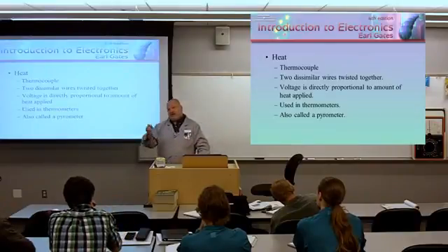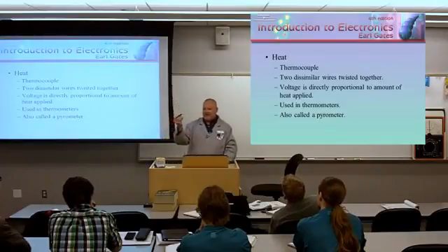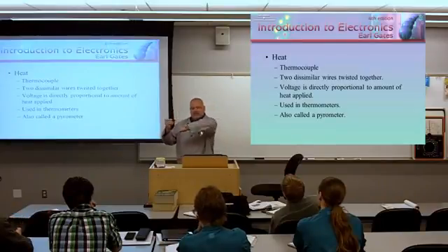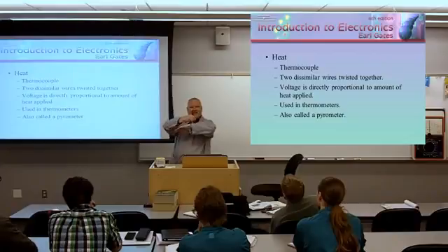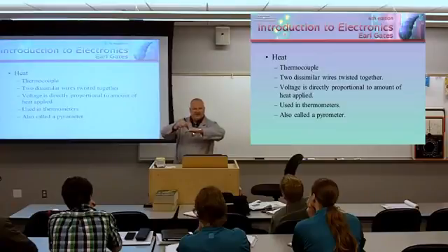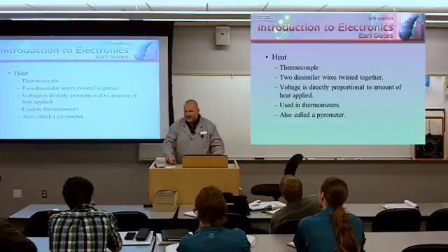So what happens is when that race car pulls in and they pull the tires off, then they could sit there after they get the car out of the pits with their thermocouple probe and then measure across the tire: outside, middle, inside, for my left rear. My right rear, take the same readings. My front tire, take the same readings. My other front tire, same readings. So you should see consistency between the two fronts temperature-wise too. That means you got the car set up so that the tires are in full contact with the road. So it's really a poor man's alignment tool.